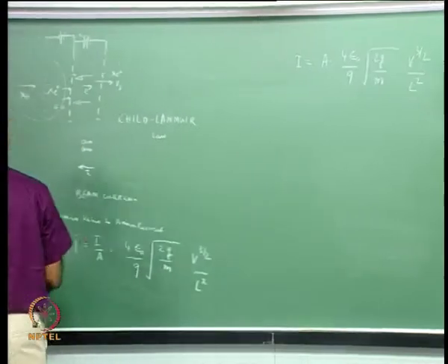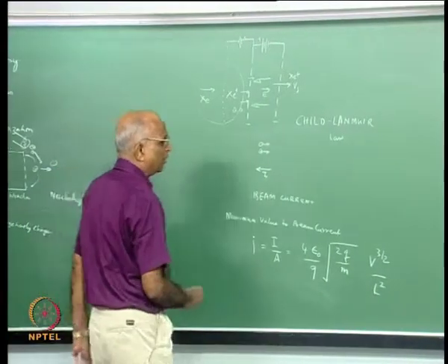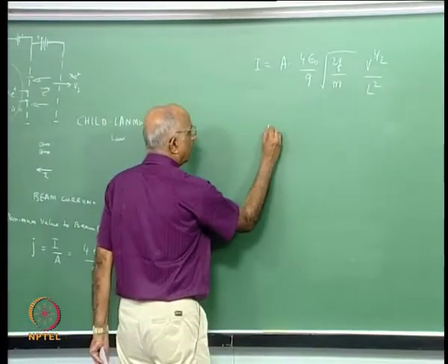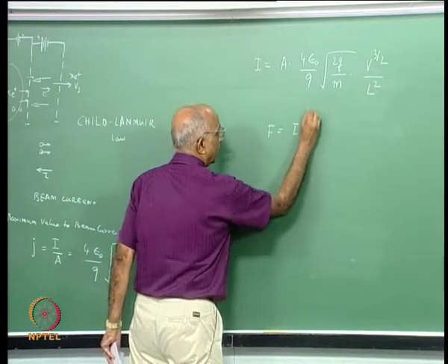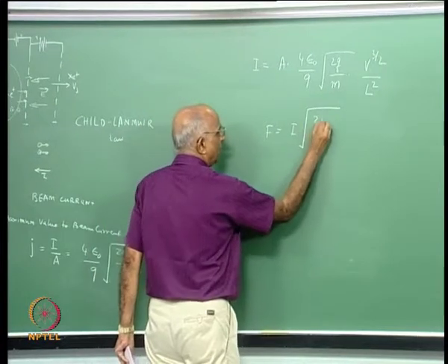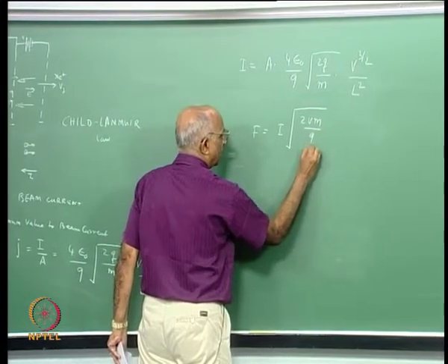But I already know the force equation, and the thrust developed by a particular ion rocket we derived as I into under root 2Vm divided by q.